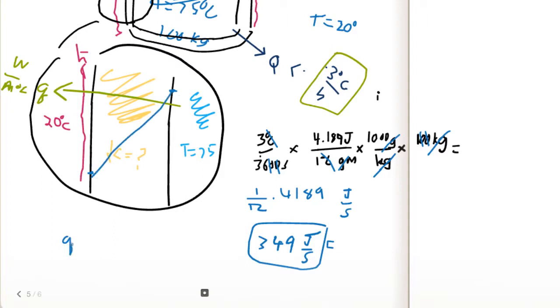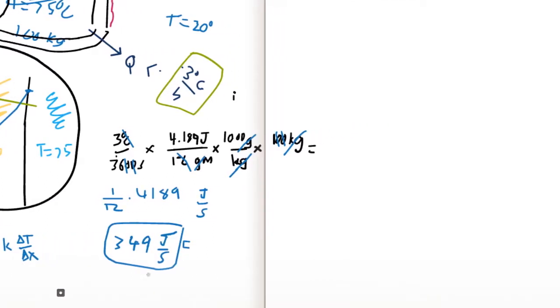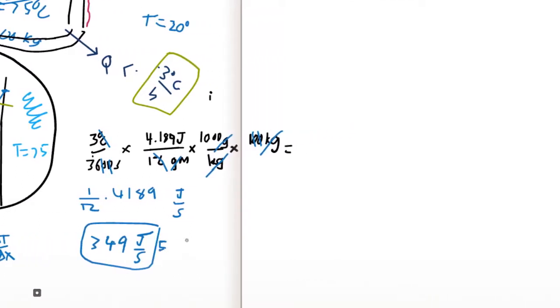We're looking at a steady state rate, so a linear temperature profile. So Q in watts per meter squared is negative K delta T over delta X. Across here, we don't know K, and we don't know X. So do we know this Q? Well, we have watts, but let's go ahead and convert that to little q, so watts per meter squared.